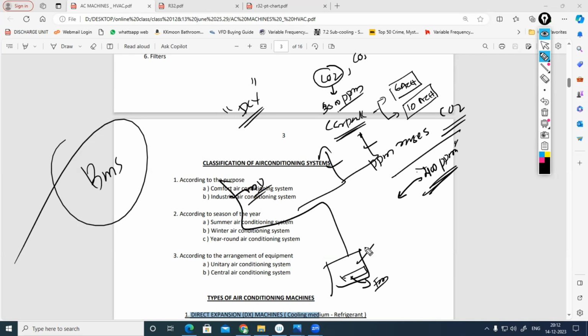So if the building is not having electricity, then at the time of power failure, we are not getting the service. We are managing, we can adjust. But even in a power failure condition, if you need the service, definitely you need an alternative power source, either UPS or a DG set. Correct. Anyhow, in developed countries, power failure will not come. But bigger equipment like AHUs or the chilled water system, chillers and all, we are not connecting to any diesel generator. Those are standalone only.